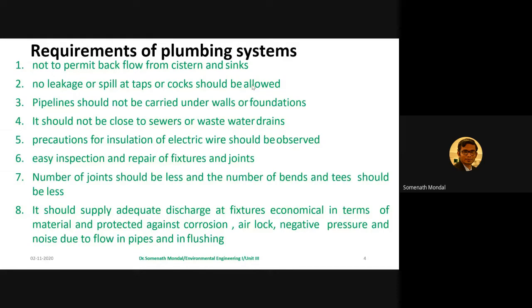So if you are laying pipelines beneath the footing or foundation, you are creating a disturbance for that foundation, which can create cracks or differential settlement in the overall superstructure, and in the long run it can damage the pipe, or there might be breakage of the pipe because of the extra stress coming on it. So that is the reason it is always avoided.